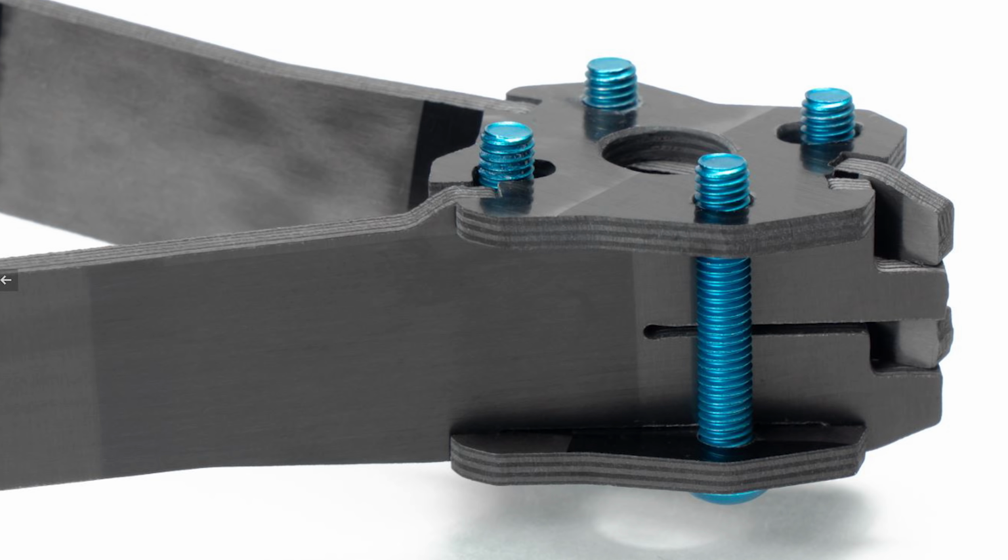So when you cut the higher strength carbons, as far as I know, your drill bits wear out way faster, right? No, that has nothing to do with it. Actually, a higher strength carbon fiber is easier to cut, because it's more brittle. Yeah, but this is not that brittle, so we're not at that level. Right, yeah. But if you're going really high, like in these high modulus fibers that we talked about earlier, they're super easy to cut, because they can crack so easily. Oh, interesting. I get mixed information from various manufacturers, as always.